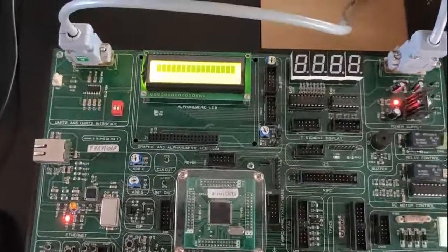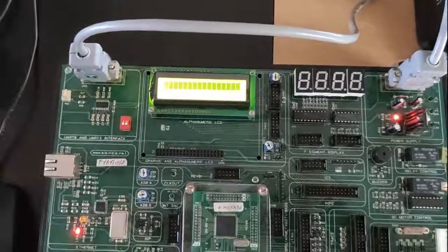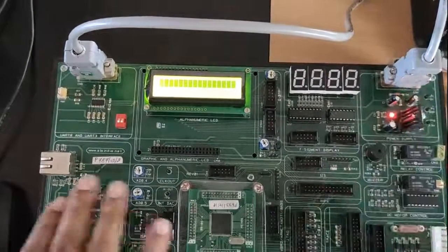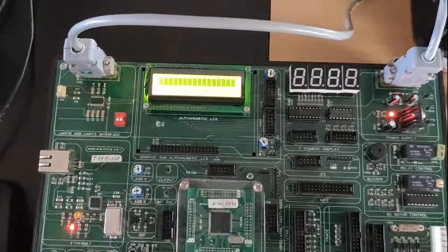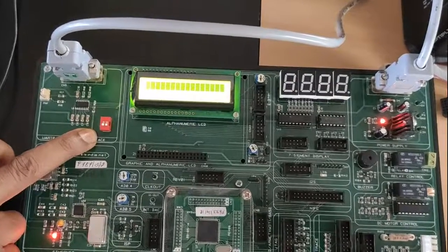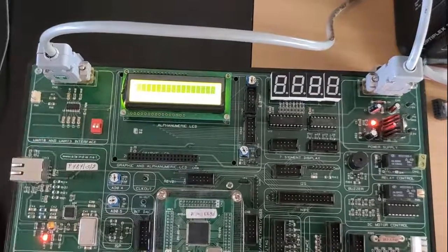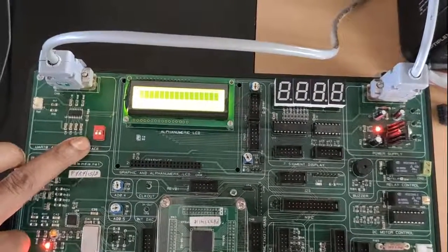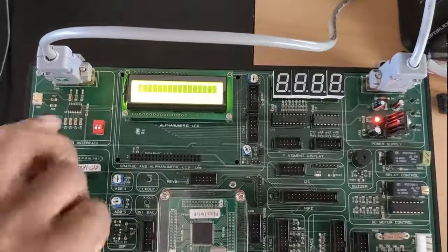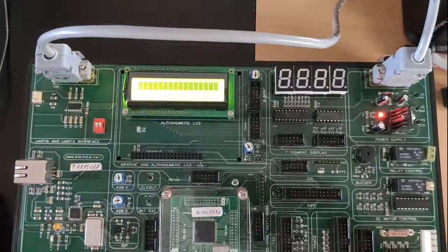So for connections, an FRC is not required here. Only the communication cable, which works as the UART mode for this experiment, is good enough, and this is the power supply as you have done. Now the important part of the experiment here is switch 21. As I said, switch 21 works in dual mode. If it is in the on condition, it will download the hex file into the hardware. If it is in the off condition, then it works for UART. So this experiment belongs to UART. So now I'll switch off switch 21, and I'll reset my code.